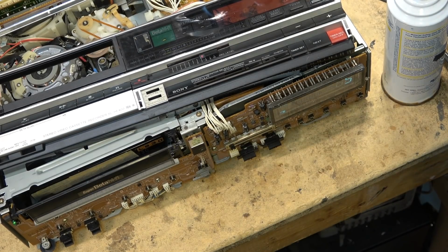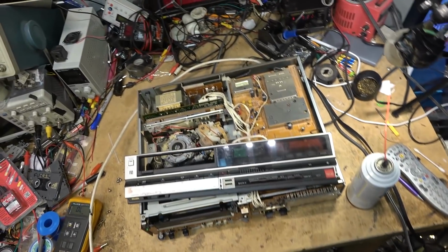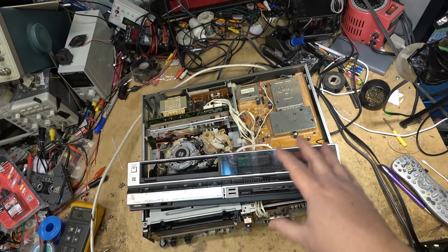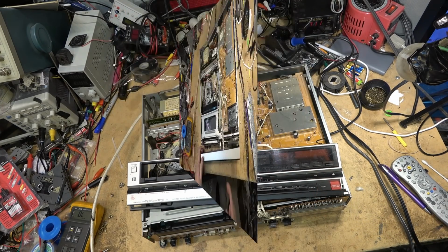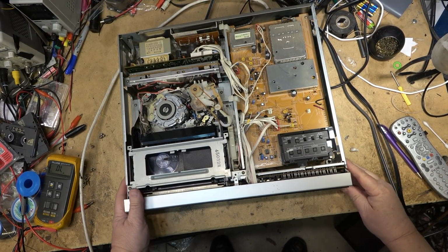Okay, now we can make a recording. I'm going to put the faceplate on, put the front panel on. We'll make a recording on this machine. I'll clean the heads, of course, before doing that. We'll make a recording, play it back. I think this machine is probably okay, other than that rewind switch and the level control. Controls all the way down at minimum, as is the front panel control. It should just snap on.